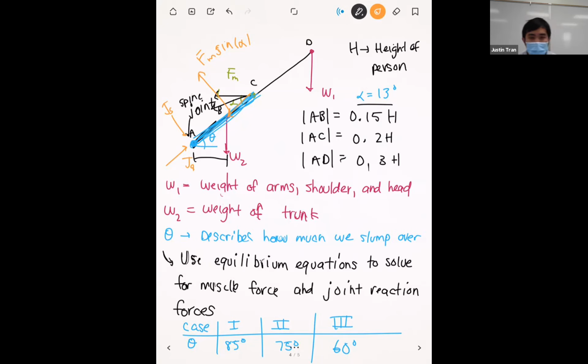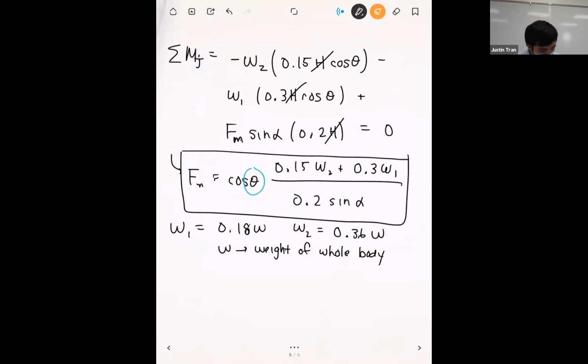that would be along this line of action, and so that wouldn't produce a torque. For these torque equations, you have to have a different mindset than for the force equations, because you have to think about what component is actually going to produce rotation. And so that's the moment equation. We'll list out what the values for this are depending on the value of theta.